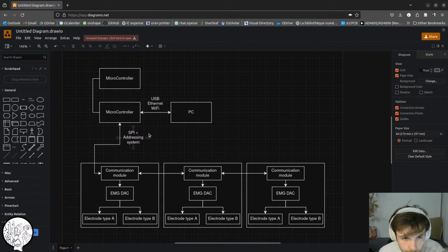The SPI protocol works with three shared wires: the clock, the data input, and the data output. What is very important is that each module can be selected independently, so each of them knows when they are talked to or when they should reply. So the naive way would be to add a wire for each of them to be able to activate them when we need to talk to them.